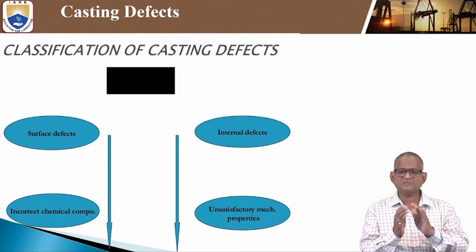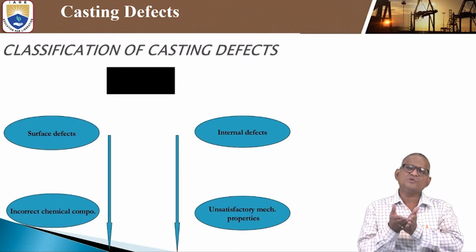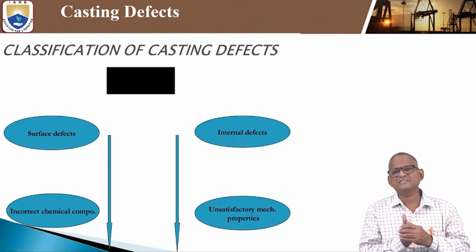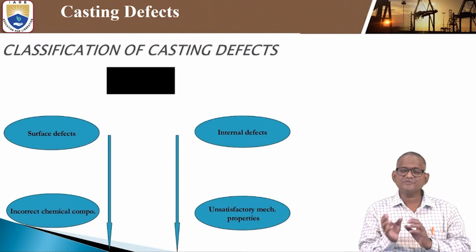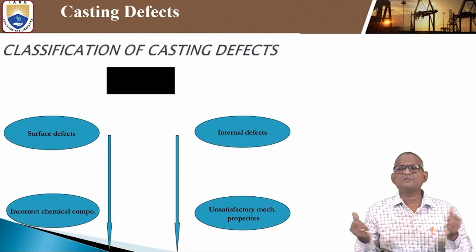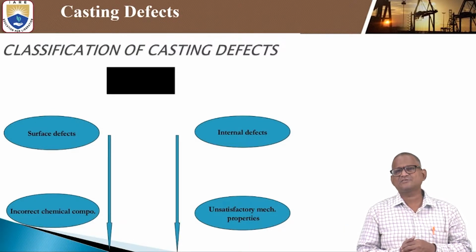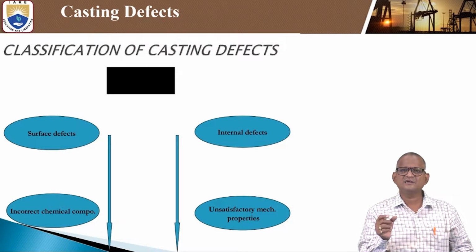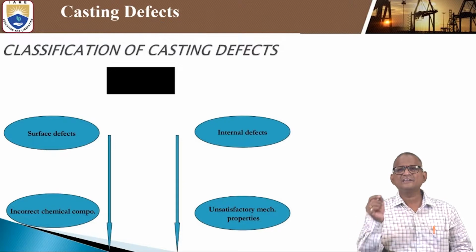Once the mold cavity is prepared, you pour the molten metal with the given pouring time, and by giving proper solidification time, the final product comes out with the shot blasting technique. Either you achieve a sound casting product or there are defects.